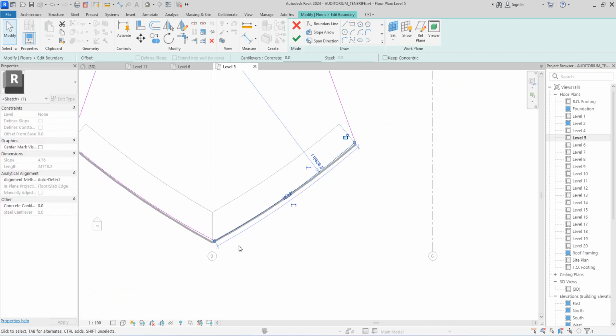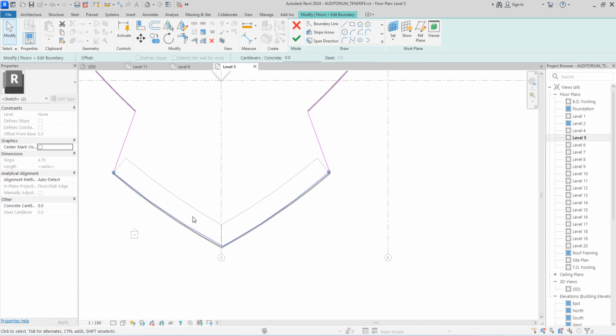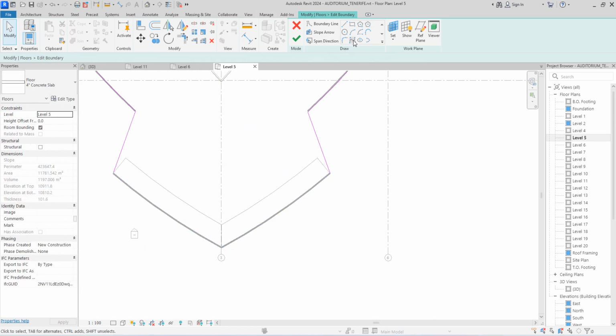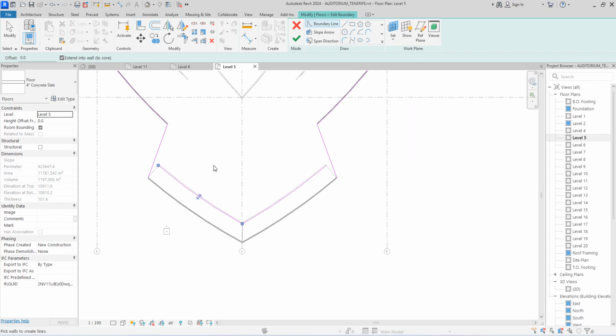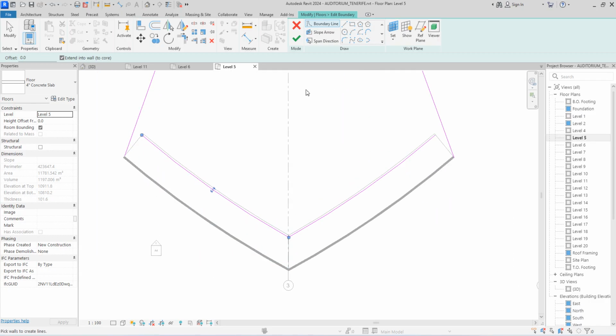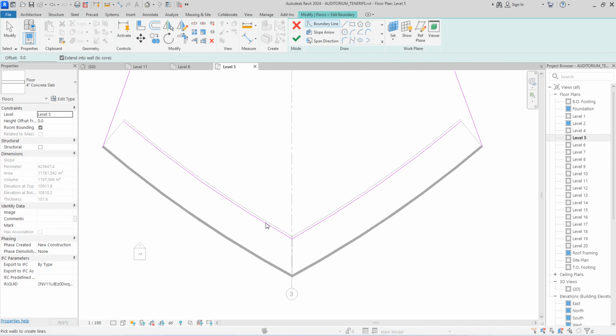If you have this like this that's covering some vision, all you need to do is select. If it goes fine, if it didn't go, you can just select wall, then you pick this wall. It's taken from inside instead of from outside, which is totally wrong. So what we need to do is delete it, or you don't need to delete.